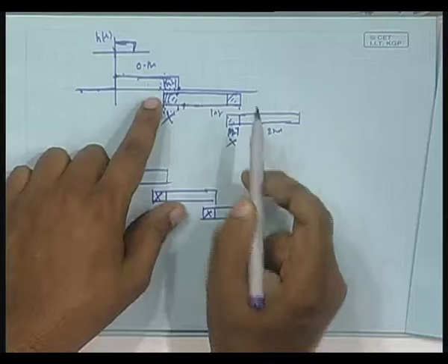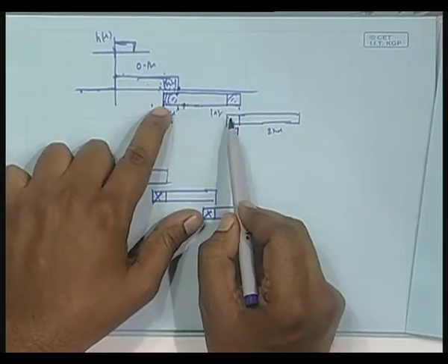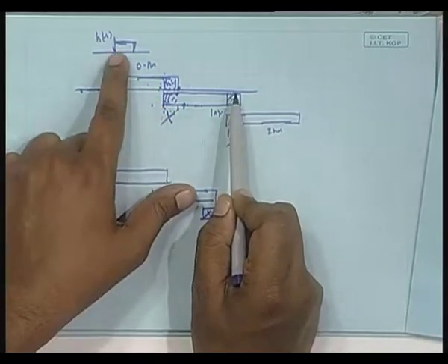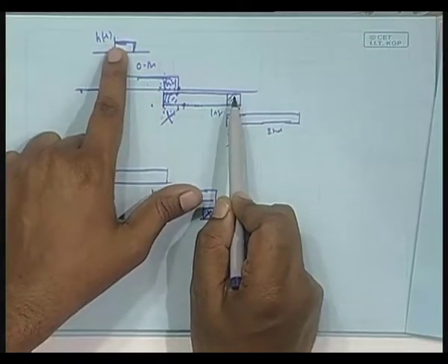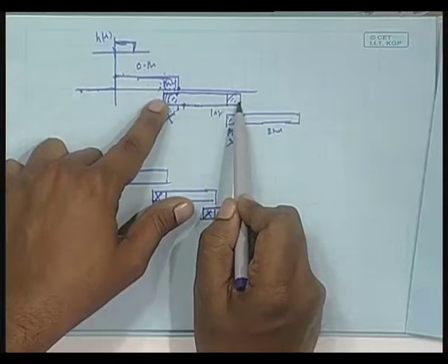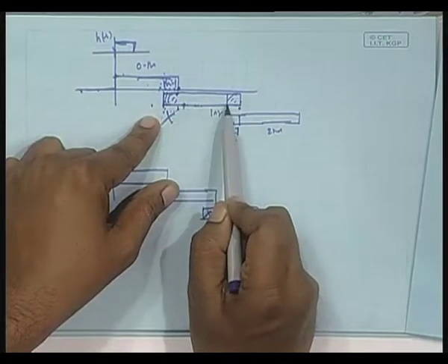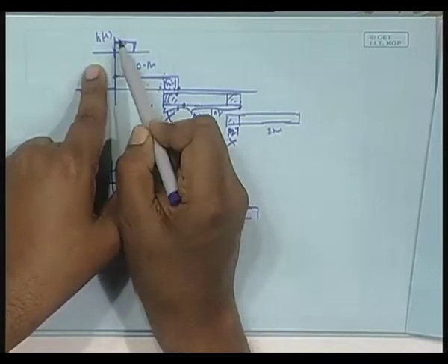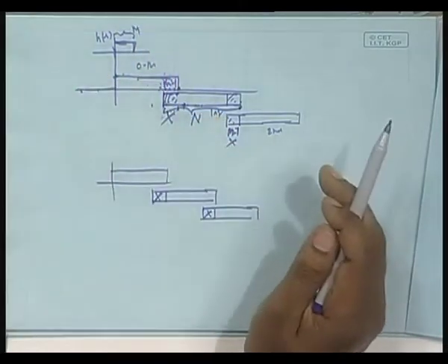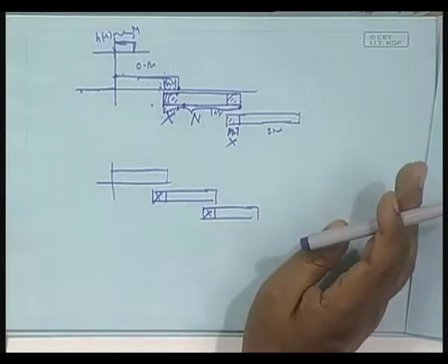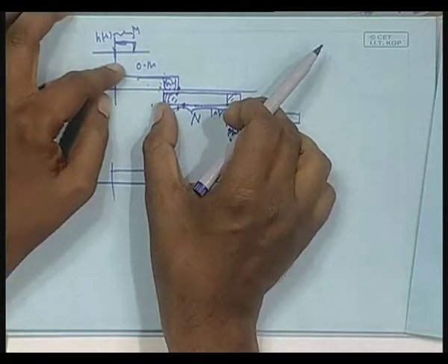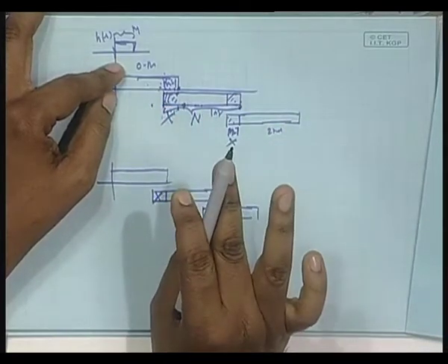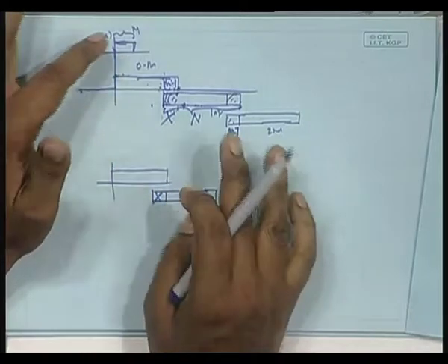What will I do? You can tell me, sir, after all you are doing convolution between this block and this entire block, isn't it? This is of length say n, and this entire length is m. So, you can tell me, sir, we all know the zero padding technique. As long as you are convolving between this and this, you will finally throw away the first few samples, I agree. But before that, let us carry out the convolution between the two.